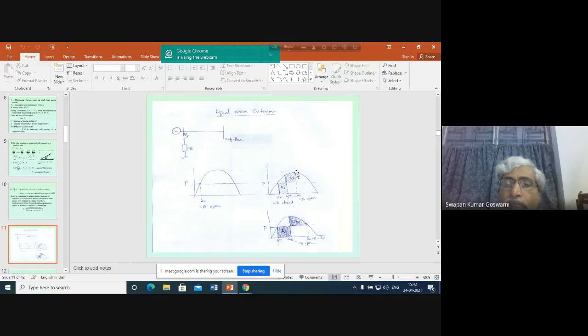Okay. So here we assume that again the synchronous speed has been achieved. When will the synchronous speed be achieved? When A1 is equal to A2. Why? Because A1 represents the energy inserted into the generator. A1 represents the energy input to the rotor of the generator. A2 represents the energy extracted from the generator. Now, what is this energy? Obviously, this A2 represents the energy that was extra, above the energy stored during the synchronous speed. And how much was that energy? It was the energy given by this area A1.